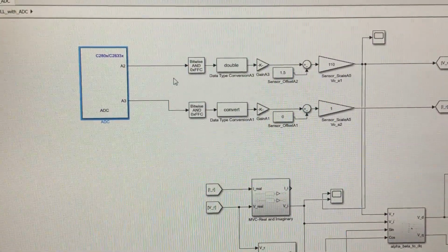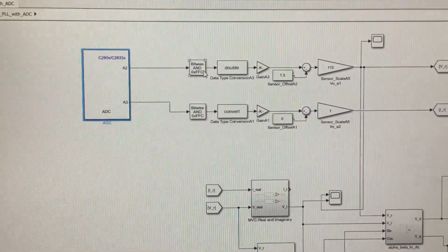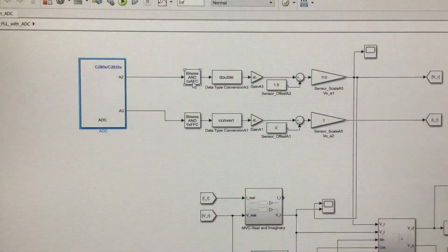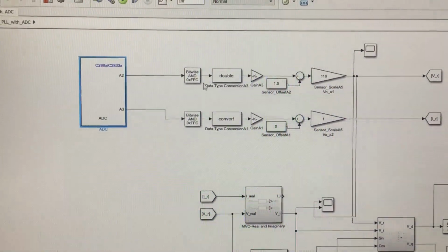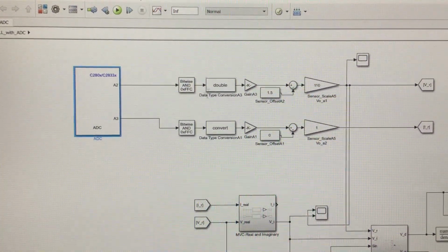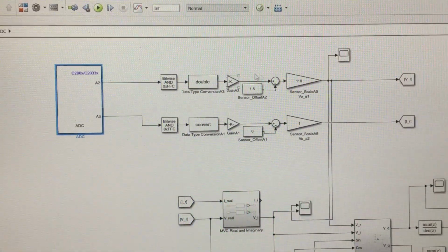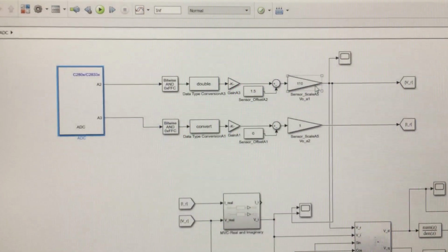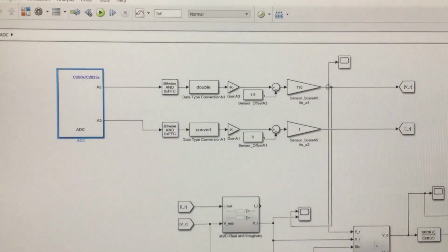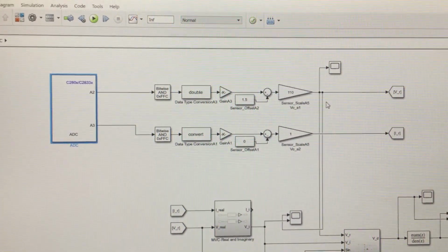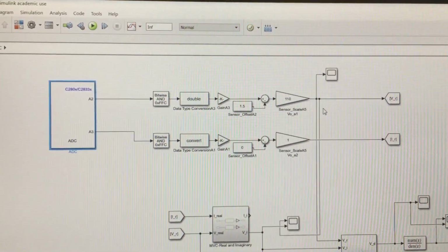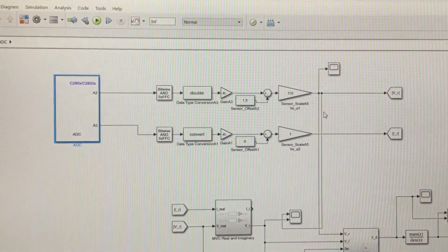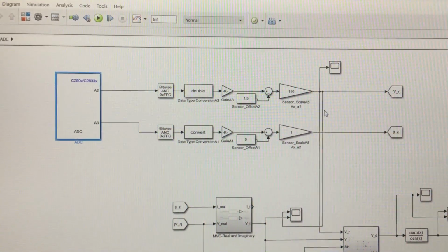After that, what happens is that we have to make use of the bitwise AND block, and after that we have to make use of a conversion block along with some of the gains over here to make sure that the output of the real signal, based on the maximum voltage at 3 volts, comes out to be around 169 volts for the D frame.